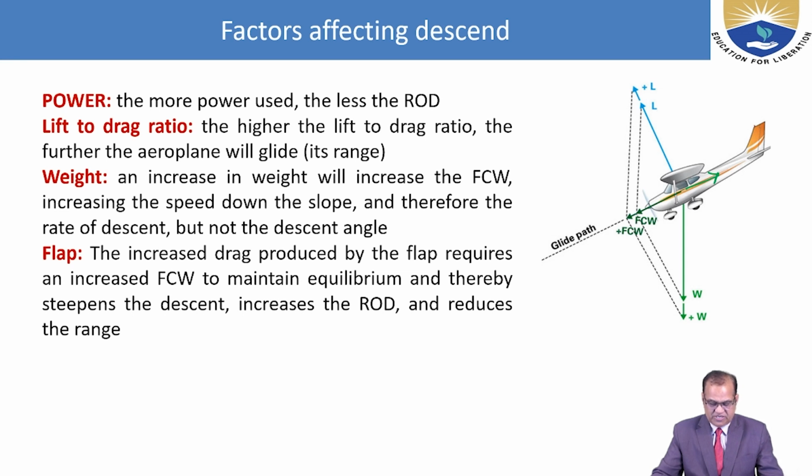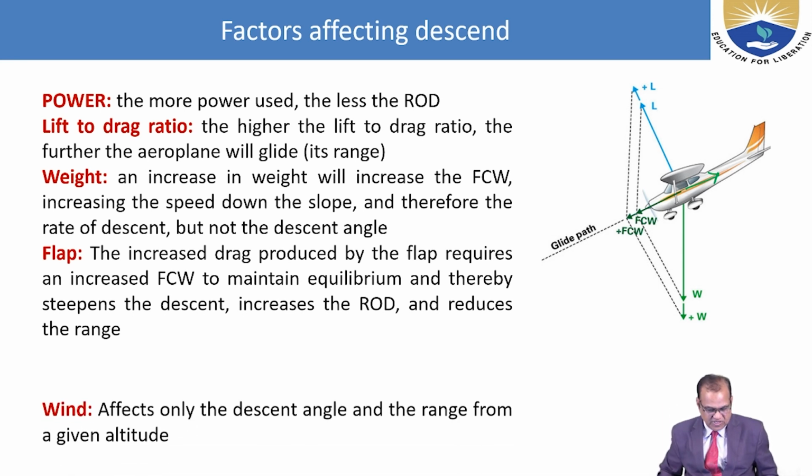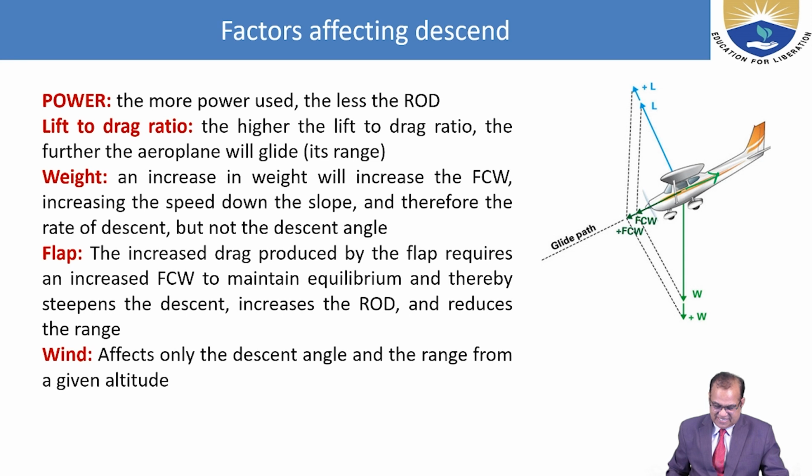As you increase the flap, more descent will be there, more angle will be there. Wind affects only the descent angle and the range from a given altitude.